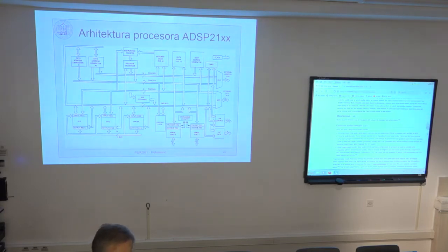So 24 bits is sufficient for only one of those 3. So actually, I execute either ALU operation, or MAC operation, or shifter operation, not some kind of combination of those. So one of the 3 is executed, but it can be executed in parallel to address modification.